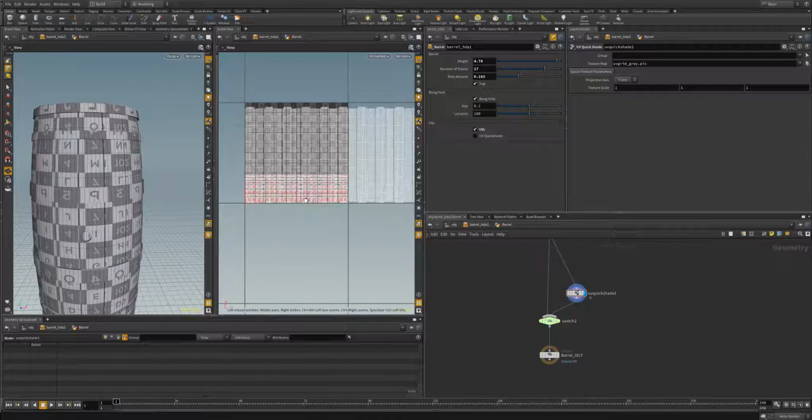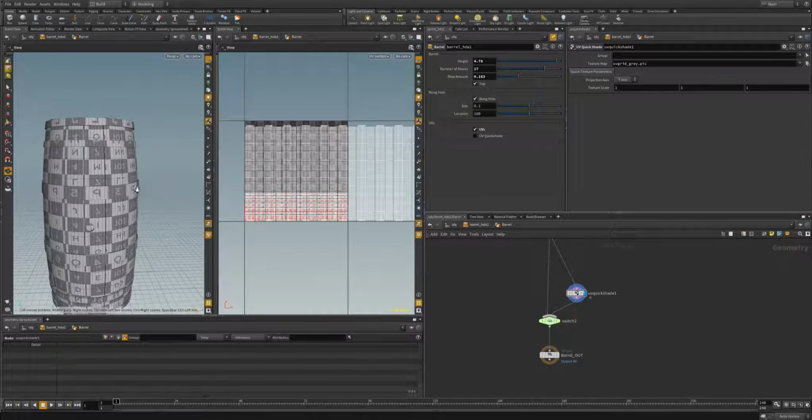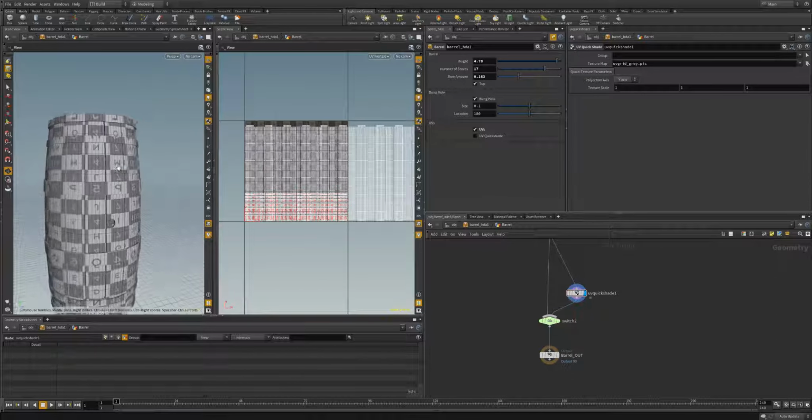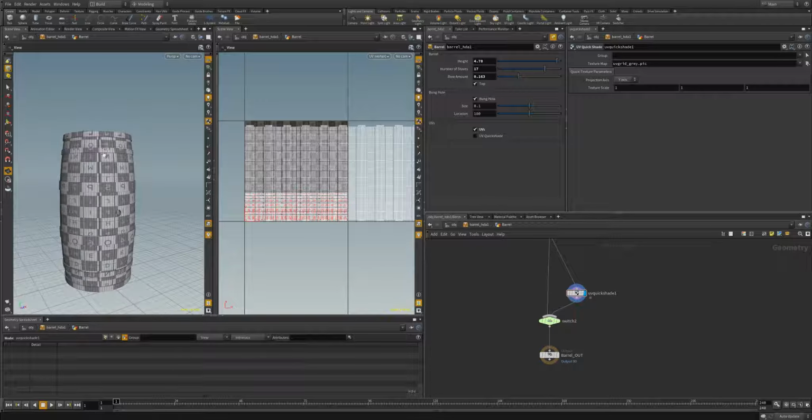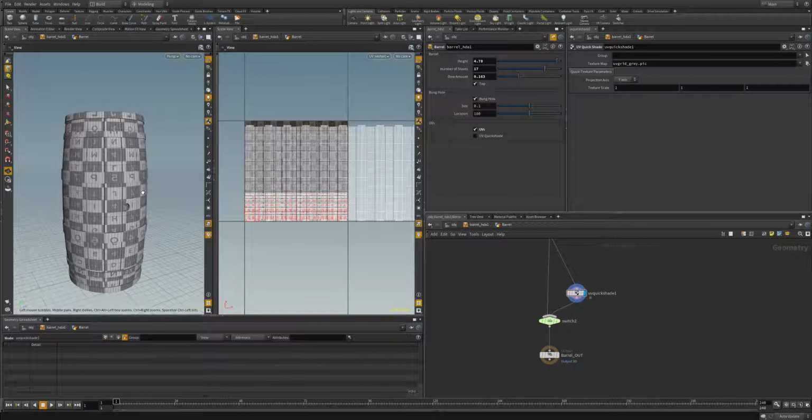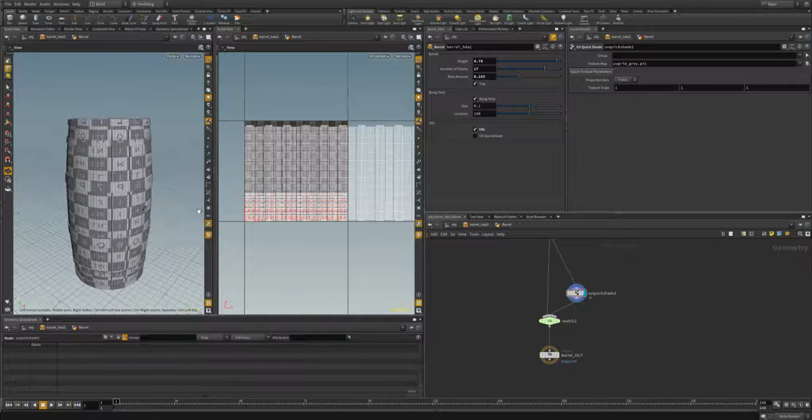And eventually, if I look here, I've got overlapping UVs, but the barrel's going to be wood and these hoops are going to be a metal or a steel. So they're going to be different UVs or different materials anyway, and at the end of the day, I'm going to texture atlas it anyway. So for now, I want to assign a different quick shade color to our barrel ring hoop UVs. So I'm just going to copy this quick shade and I'll paste it in here.